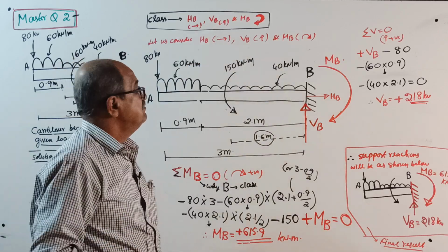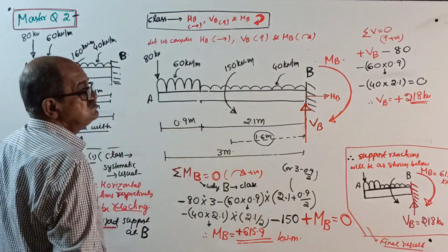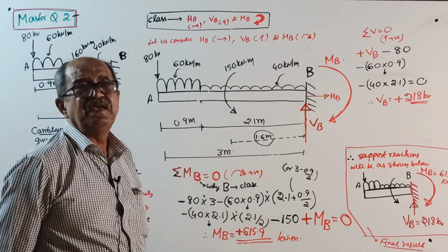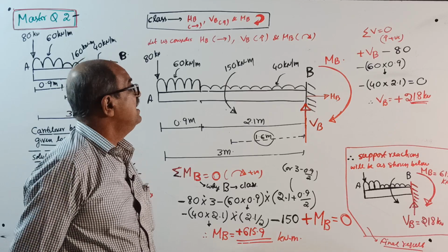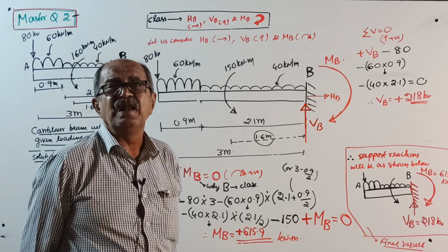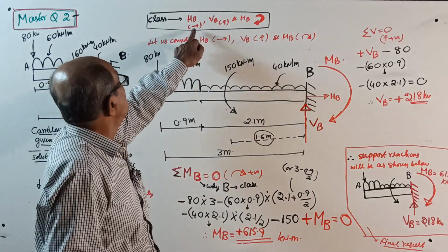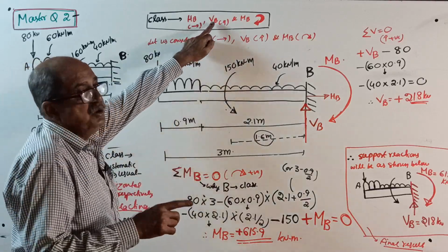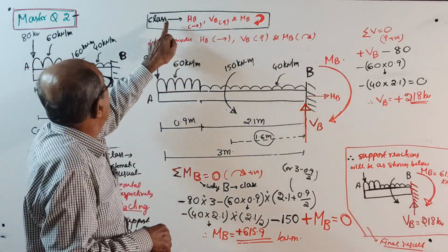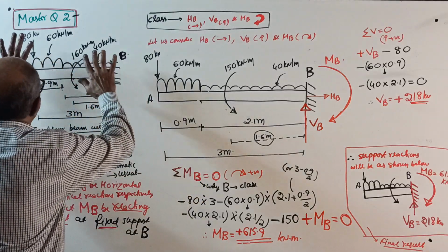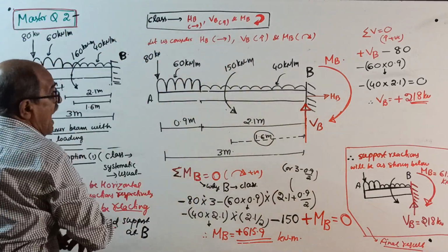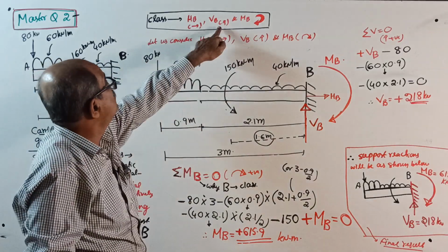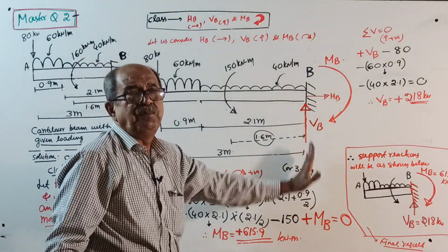First, HB: there is no horizontal load. And just one horizontal reaction cannot balance anything. It cannot be balanced. Therefore, for this question, there is no horizontal reaction. Still, systematically, I will take it to the right side. Now, VB. I already told all this last time, what all I dictate, you are right. The loadings are acting vertically down, that is action. So the reaction, the vertical reaction, will be up. That's why I am considering VB to be upward.